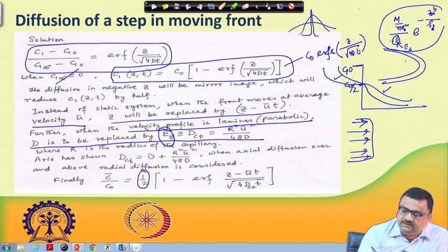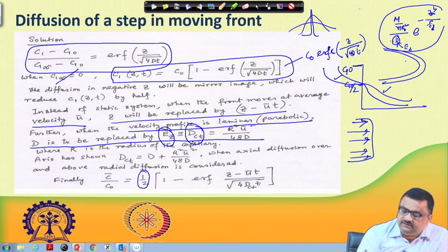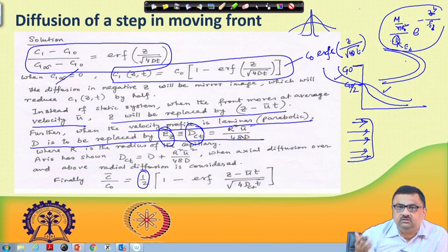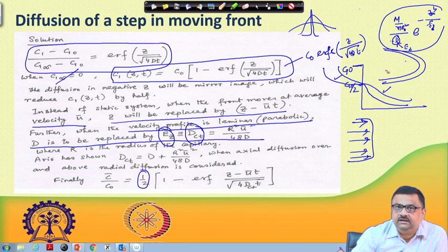Now, in case of a step change, the general literature gives this as the dispersion coefficient for a capillary: Dct, which is the same as r, basically the radius of the capillary, squared, times average velocity squared, divided by 48D. Further, there is one point I must note here: beyond Taylor, Aris, who is the next scientist who worked on it, showed that if somebody wants to consider axial diffusion, you remember when Taylor did this analysis, we considered axial convection and radial diffusion.